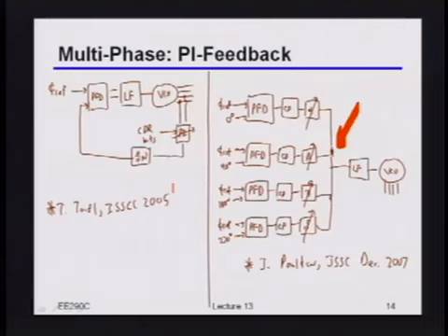Make sense to people? Maybe this doesn't matter, but any mismatch on the paths on the feedback, at least for the dividers, I guess the CDR adaptation takes care of it? Well, no. If there really was mismatch on the feedback paths, that could translate into errors on the step sizes of your phase interpolation codes.